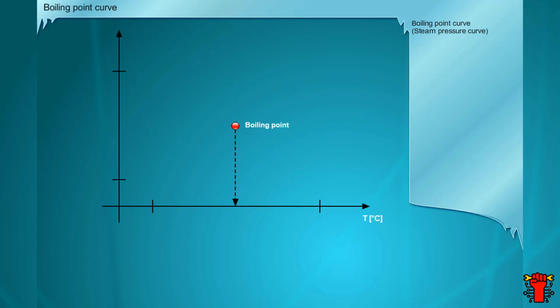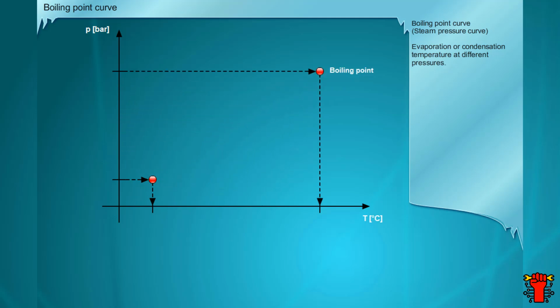The boiling point of a substance is the temperature at which it changes from a liquid to a gas, and vice versa. Therefore, the substance evaporates when heat is applied or condenses when heat is removed. From the preceding pages, however, you have already learned that this temperature depends greatly on the amount of pressure applied. If the pressure is reduced, the boiling point drops, heat is absorbed, and the refrigerant evaporates, even at temperatures below zero. On the other hand, the boiling point increases as the pressure increases. The refrigerant gives off heat and condenses, even though it is hot.